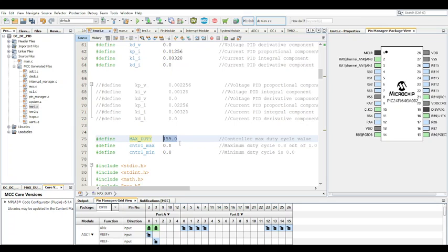It's a max of 1. The PID just outputs a max of 1. It doesn't go past 1. So it's almost like unity. And after that max of 1, you have to multiply it by this, obviously, to scale it to the proper duty cycle for the microcontroller, right?